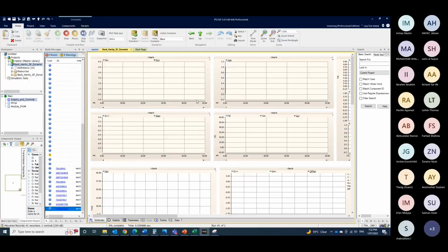It takes some time to compile, but when you have repetitive tasks to do, like change the fault level and do it again, what you can do is take a snapshot. If I do a snapshot now, next time I run the snapshot, it will start from this point onward, meaning it doesn't go through all that compilation. So that's one way to shorten the time duration.